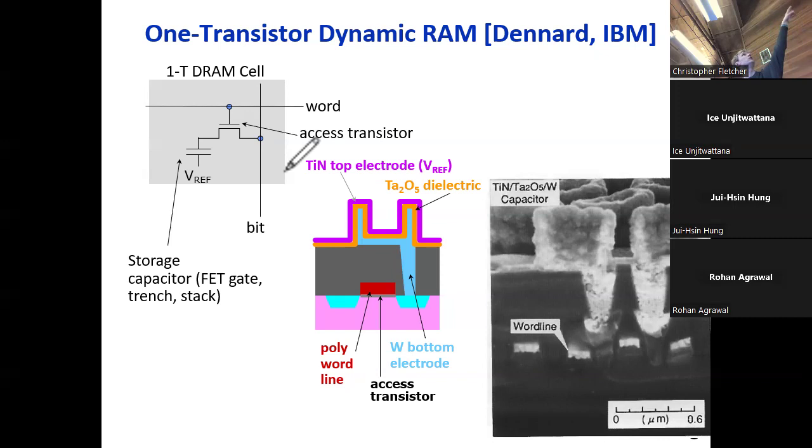And the thing in the middle, the NMOS or access transistor, and the capacitor that on the other side is going down to the reference voltage or ground, is how we actually store the charge. Who here in some class has seen an NMOS or a PMOS transistor, this symbol here? Okay, almost everybody. So people know that this is a switch.